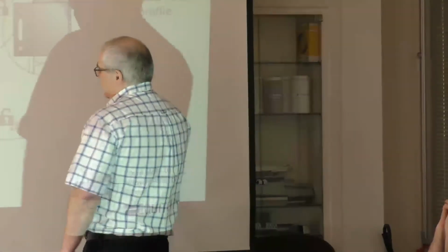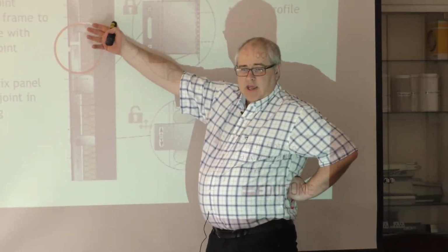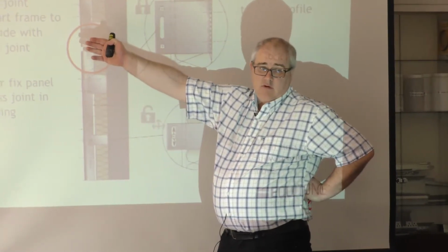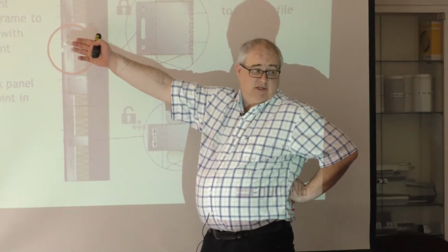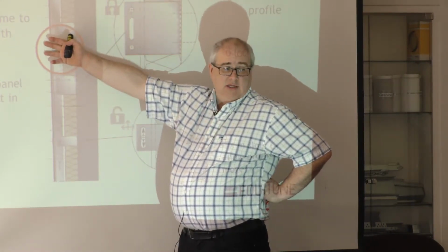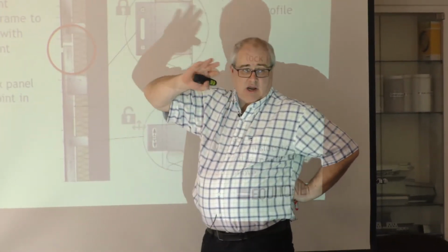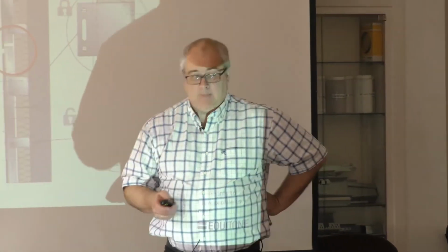The reason why this is dramatically important for us as panel manufacturers is that aluminium moves like crazy, like a disco dancer. Our fibre cement doesn't move as much, near as much, maybe 20% as much. So as this thing is moving crazy behind it, we're not growing or getting smaller at the same rate. And the risk is that when this goes up and down crazy, you're going to start cracking our panels and our boards. And I know straight away when the frame has gone belly up on a particular job because of the way the patterns of the cracks on the boards have happened. Okay?